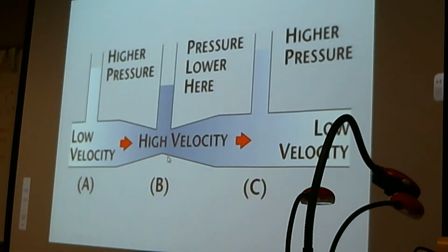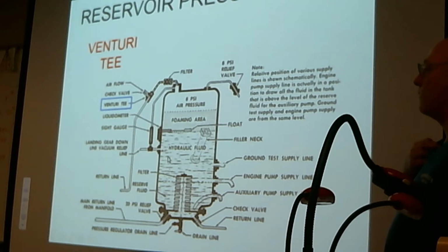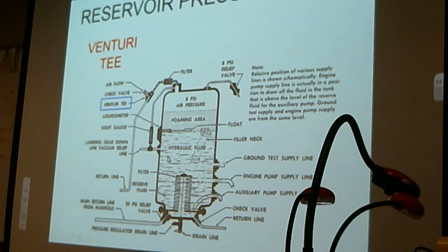Doesn't it tend to get air in the hydraulic fluid? Well, yeah, the problem is, the way that they have it illustrated, it looks like it dumps directly into the reservoir from the top. But in actuality, in many of the reservoirs, they've got a separation plate or a foaming area that allows that air to somewhat separate before it gets to the inlet of the pump. So the answer is yeah.